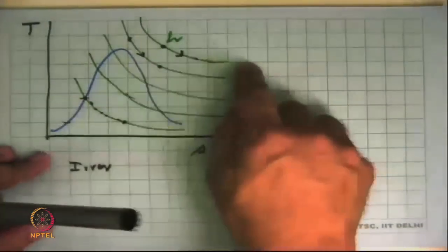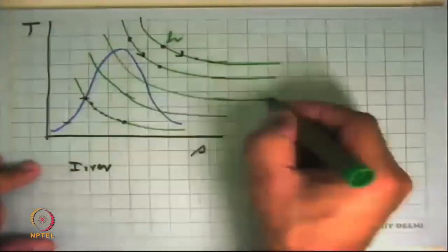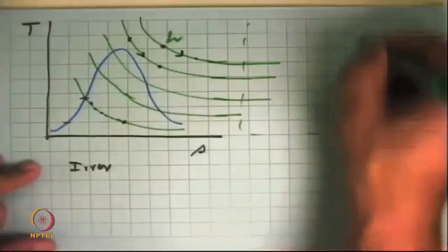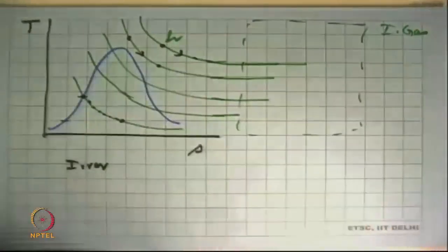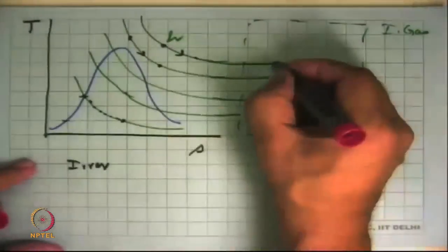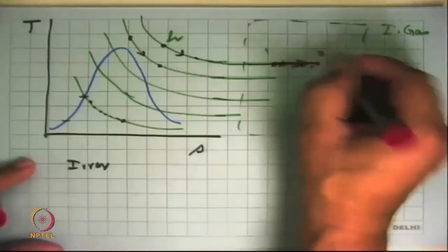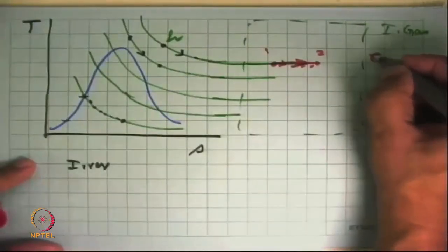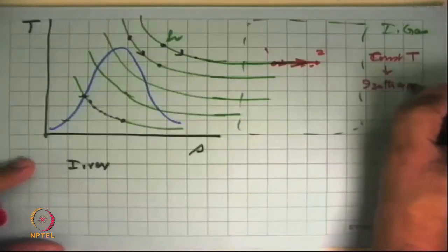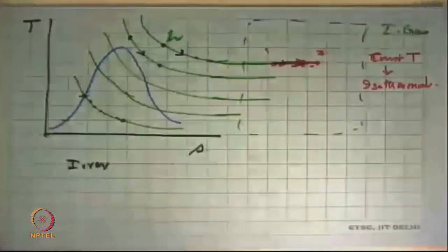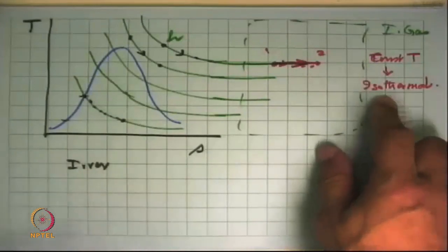And the only other thing that comes out to be interesting is that the constant enthalpy lines further away become constant. And so this region, which is the ideal gas behavior, these lines are constant, which tells you that if you throttle an ideal gas from there to there, this should be a dotted line, it's an irreversible process. Throttling is a constant temperature process, isothermal. And that means that that's only when the velocity changes are very small.